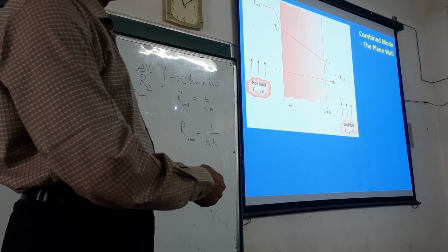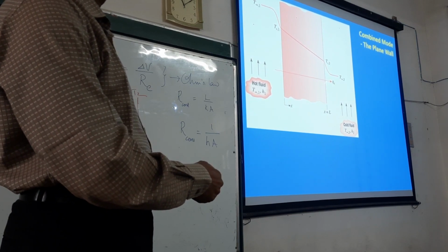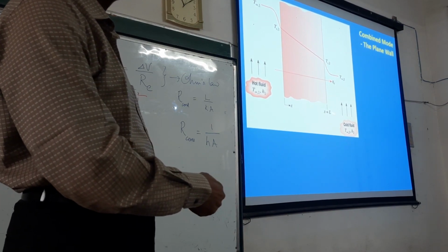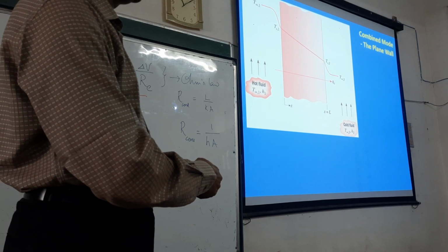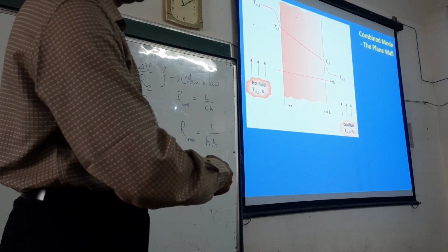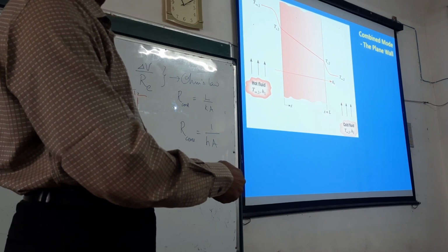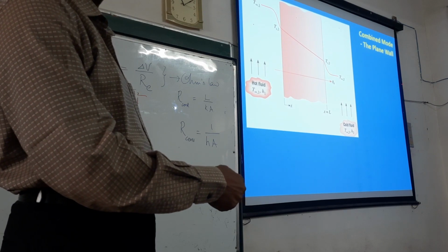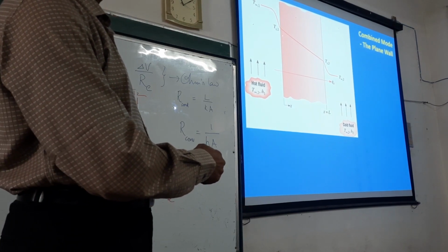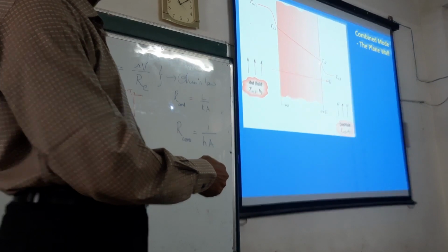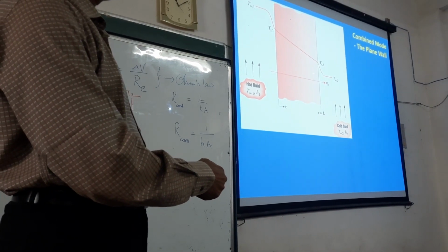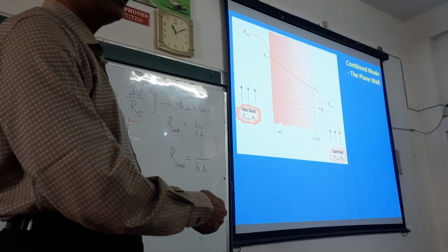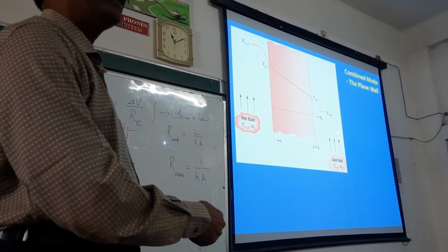Now, within the plane wall, from one side of the wall to the other side. The potential difference for heat transfer is, please remember, the temperature difference between hot and cold fluids. So heat is flowing in the x direction as shown here, and therefore the temperature is dropping in the direction of x. Because of the temperature difference within the wall, the heat transfer here is by conduction, and thereafter between this surface and the surrounding fluid, which is cold here, again convection.